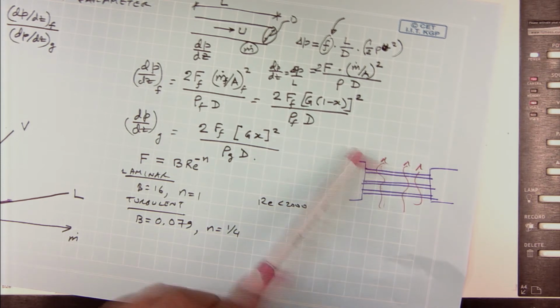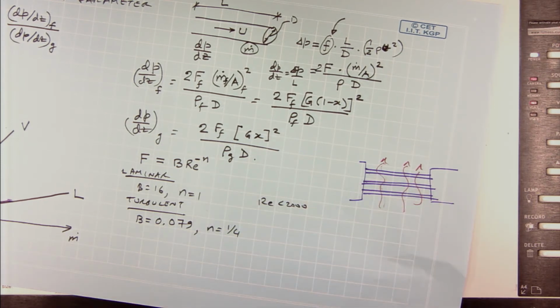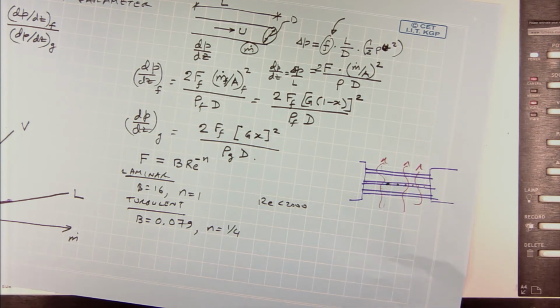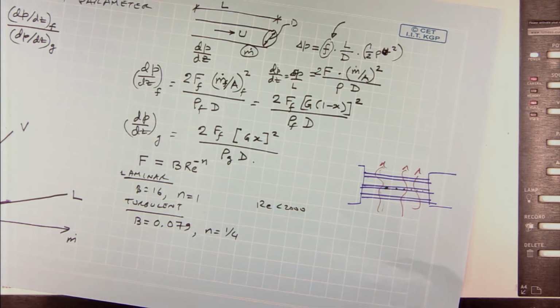Okay. Now, if I have a parallel set of these pipes, it creates its own problem. Let us say all of them are pumping pure liquid, and then one of them forms a small vapor bubble in the pipe. What has that done to the average density, or average viscosity, of this flow? If I were to treat it as a homogeneous fluid, now I have to replace it with a fluid which has a lower average viscosity, and because it has a lower average viscosity, what happens? The pressure drop in that pipe is smaller.